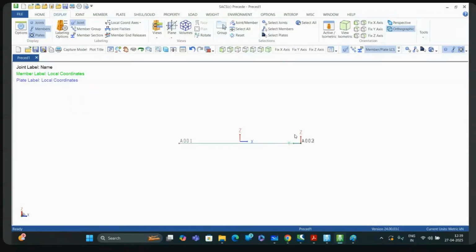This will be very handy because I took almost 6 months to identify there is an option called orthographic when I started my career. Because we created big structures like 20, 30 meters, every time I took a screenshot, it was not coming out proper. Because in ANSYS and all, it should come proper. Then only we identified that there is something called orthographic over there. Even our trainers didn't tell me. So that is also a very handy feature.